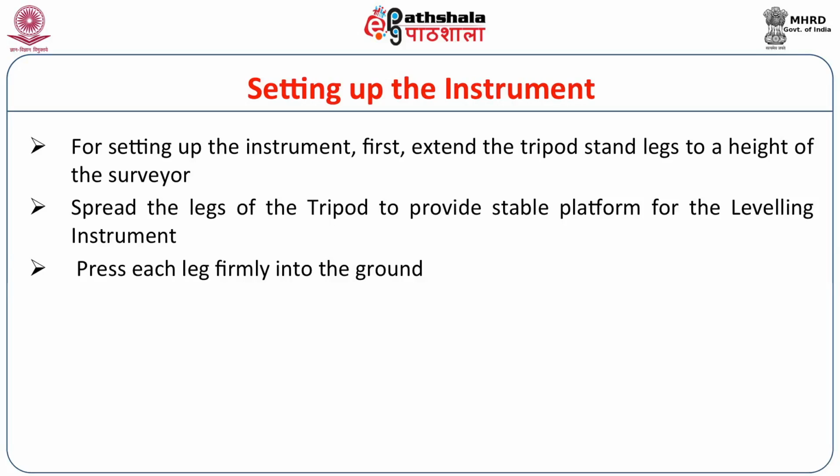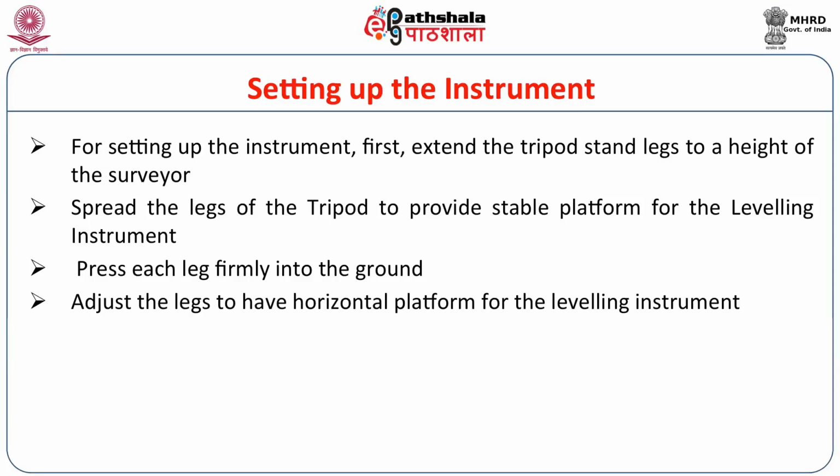When we spread the legs, we have to ensure that the legs won't slip at a later time. So, for that we have to see that the legs are firmly embedded in the ground by pressing with a foot on the shoe, that is the tripod shoe. We have to press the shoe into the ground, so that there is no possibility of any movement in the position of the tripod legs.